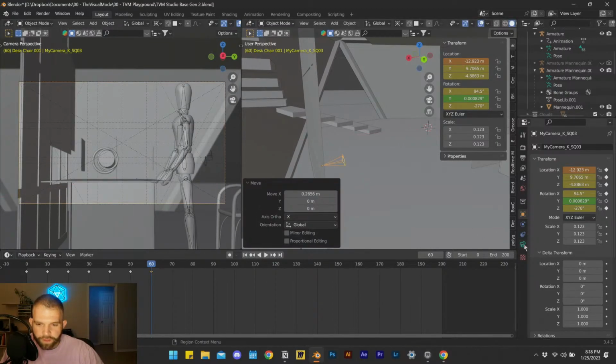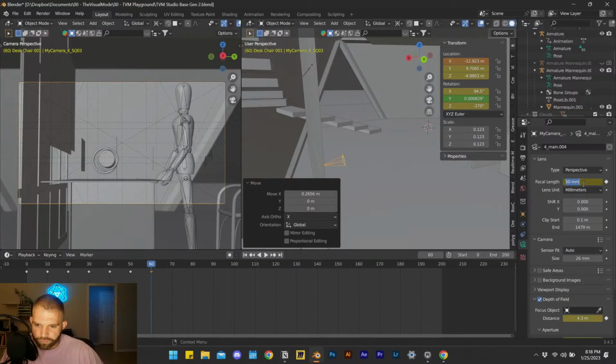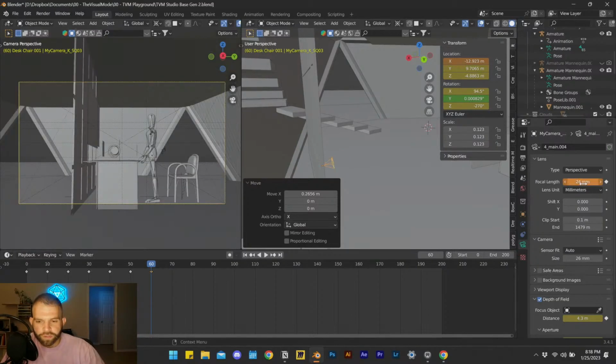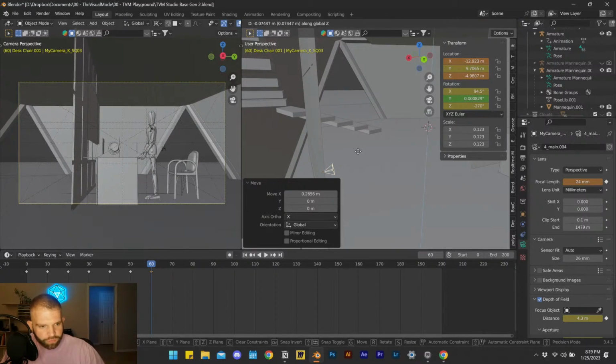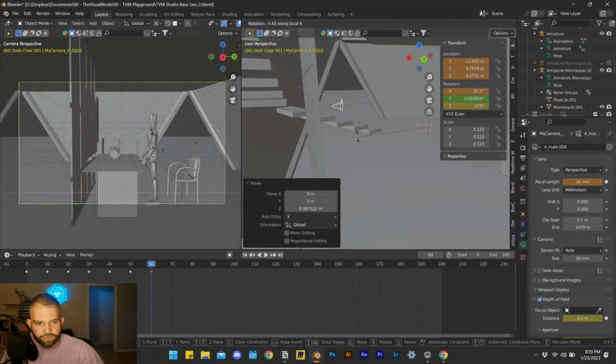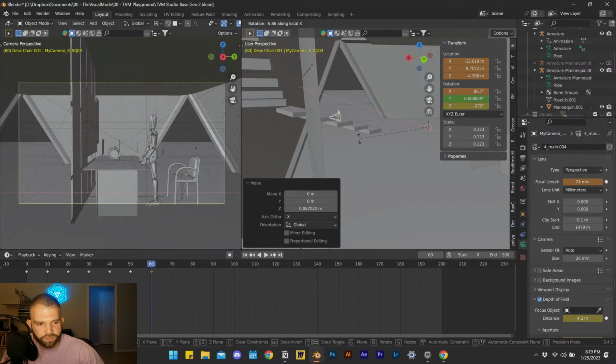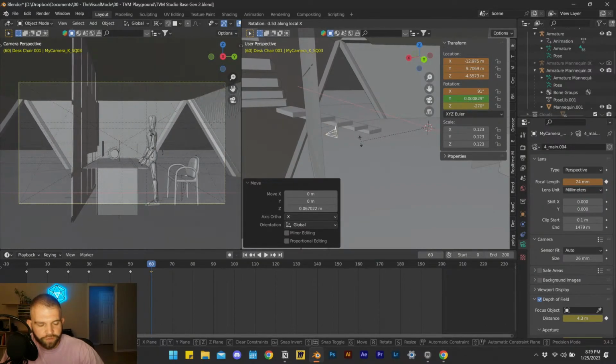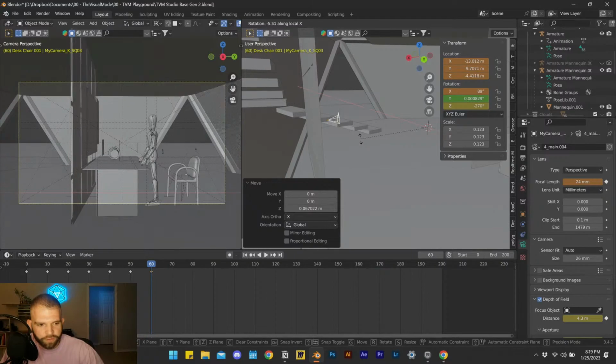And then what I'll actually do is make it a bit more of a wide angle. So since he got up, for this shot, we'll reveal more of the room and more of the environment, right? Maybe not more wide angle. I'm actually just going to move it a bit lower or angle it lower. So RX. If I do RX, it's going to be global. But if I do RXX, if I hit X twice when I rotate, there we go, it's going to be based on the camera X rotation. So that's what I want, revealing a bit more, but kind of looking a bit down.